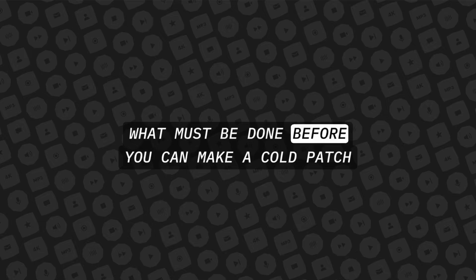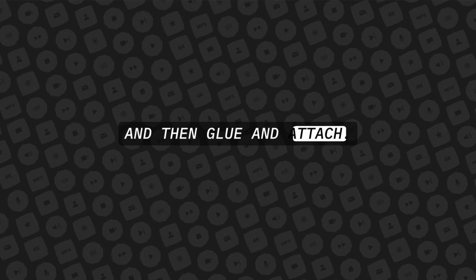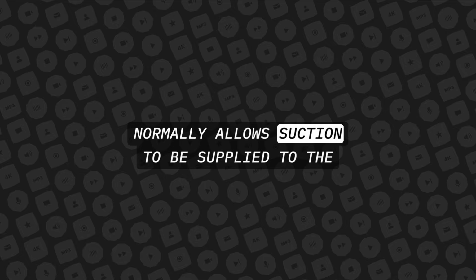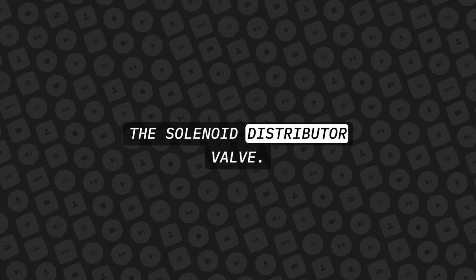What must be done before you can make a cold patch repair to de-icer boots? Clean, rough the surface of the boot and patch, and then glue and attach. What component of a pneumatic de-icer system normally allows suction to be supplied to the boots to hold them down in flight? The solenoid distributor valve.